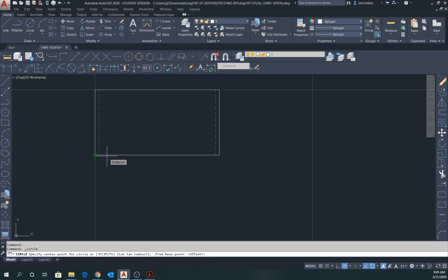So I'm able to have this drawing on another computer screen as I'm drawing it. So anyway, after we hit our snap from, we click on this point. Once we click on that point, we can type at 2.925, comma, 0.614, hit enter. That puts our circle in, and then we just type 0.375. We hit enter, and that puts the hole in.